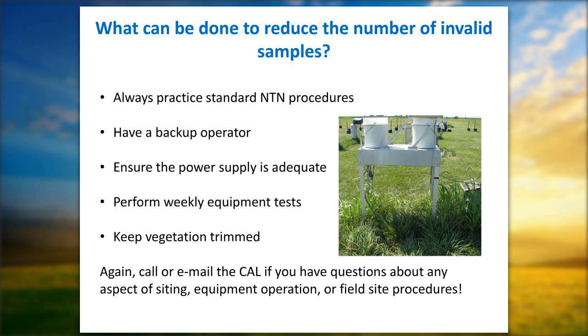Understanding the function of these collectors: when you put together a battery bank and run those in parallel, say a 4-battery or 2-battery set, the collectors and the equipment will only work as well as your worst battery. So a recommendation a couple times a year is to take the batteries and have them load tested, just checking whether they're going to stand up for another harsh winter or what the occasion may be.